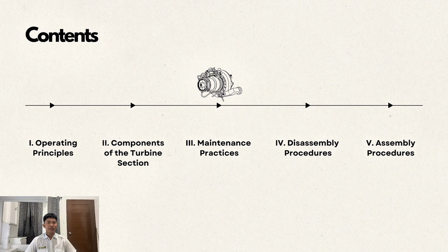This part of the report discusses the safety protocols when dealing with the Allison 250C20 engine. But before maintenance execution, safety must be our number one priority because skills cannot be applied without a safe mechanic. So, use proper personal protective equipment or PPEs such as aprons, gloves, and goggles. Be cautious of hot surfaces and pressurized systems. Follow proper cleaning and fire safety procedures, especially when using chemicals.